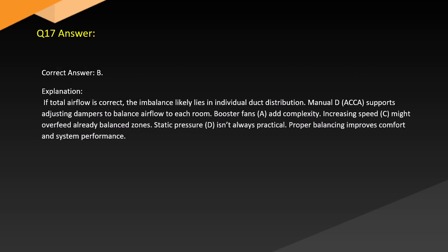Answer. Correct answer B. Explanation. If total airflow is correct, the imbalance likely lies in individual duct distribution. Manual D supports adjusting dampers to balance airflow to each room.